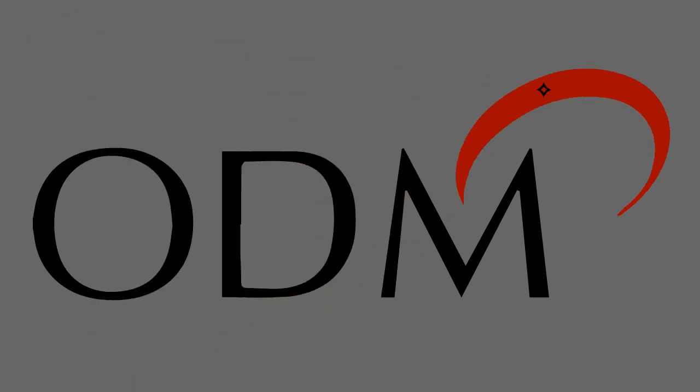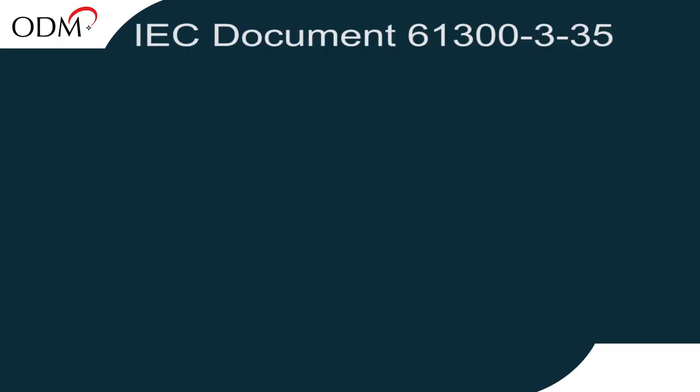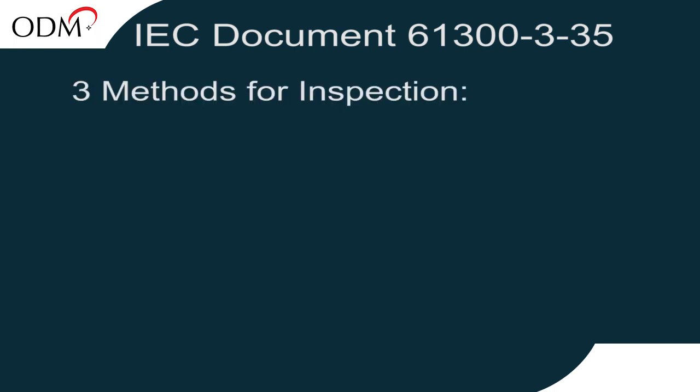This video will explain the manual grading process for fiber end faces using the INSPEC software from ODM. According to the IEC's International Fiber Testing Standard Document number 61300-3-35, there are three acceptable methods for performing fiber inspection.